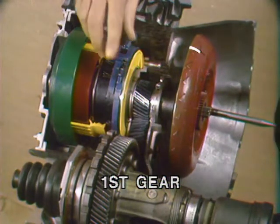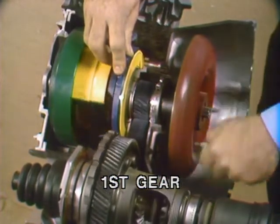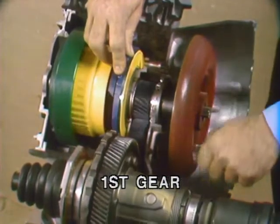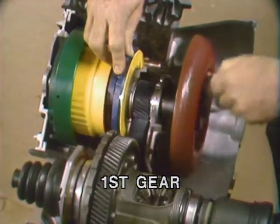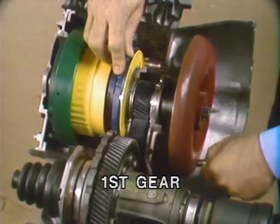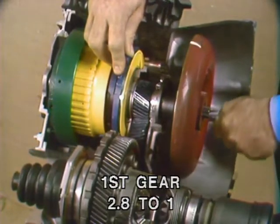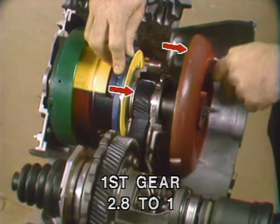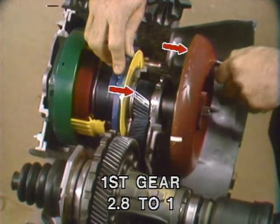This time, Joe is tightening the band around the forward sun gear drum, and he will again drive the turbine shaft. Now, as you can see, the planet carrier and final drive input gear are turning the same direction as the input shaft, but at a reduced speed. In first gear, the ratio is 2.8 to 1. Count the turns of the turbine. 1 turn, 2 turns, almost 3 turns.